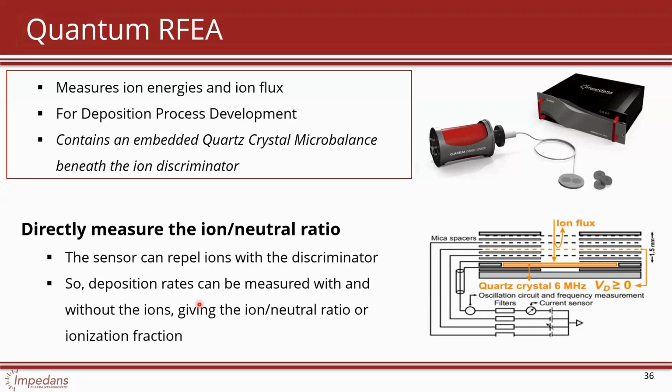Okay, you mentioned ion neutral ratio. What is the role for the neutral argon considered? Ion neutral ratio is more important for the metals. Okay, I think I understand your question here. So for ion neutral ratio, what matters more is, let's say if you're doing metal sputtering, the ratio between, like, sputtered tungsten. When you sputter something, it doesn't have to be charged, it may be neutral.